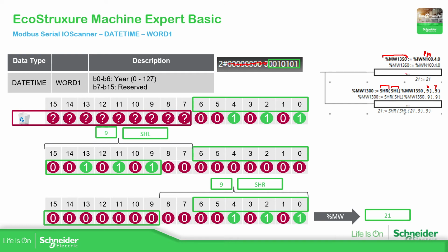And in this case, I'm lucky enough that I receive zeros, but the truth is that I really don't know if it's 0 or 1 on the power meter. So I'd rather delete all this part. So in order to delete this part and take only these 7 bits that I want, from bit 0 to bit 6, I need to move everything to the left.